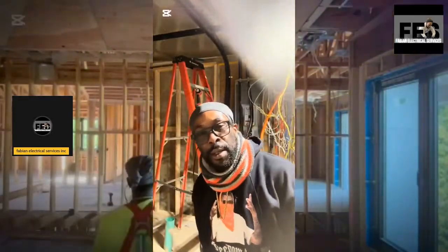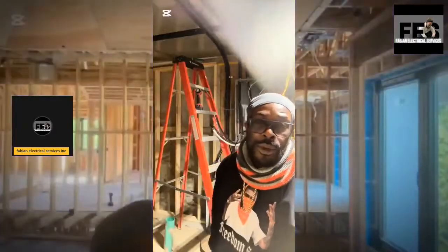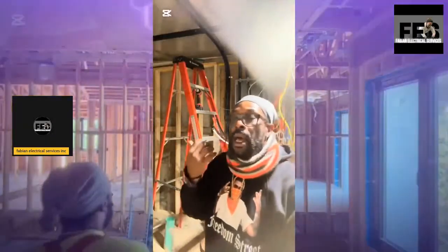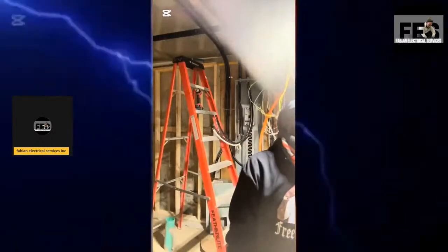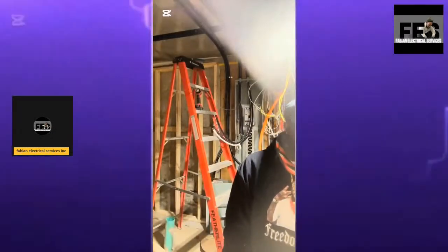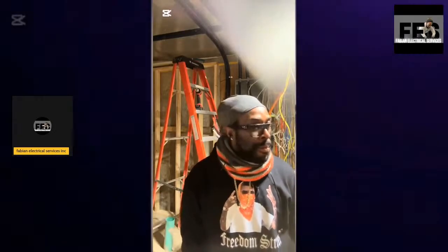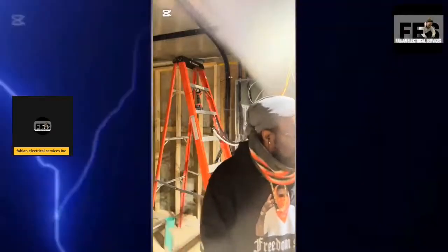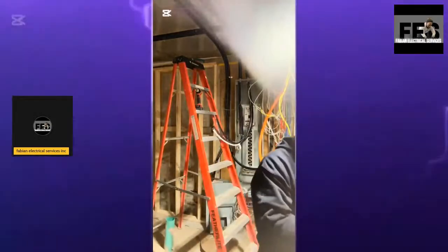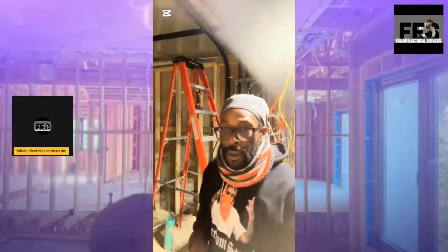And when it comes to your phasing, red, black, blue, those are the tapes that we're going to be using when you want to phase your conductors. Sorry about that. So yes, those are the rules that are all inside of the code.